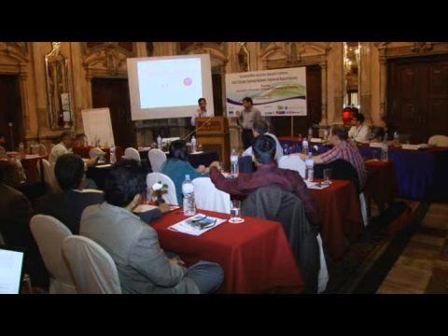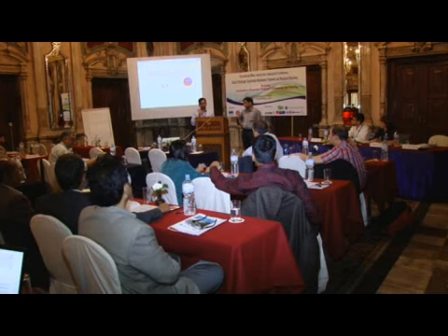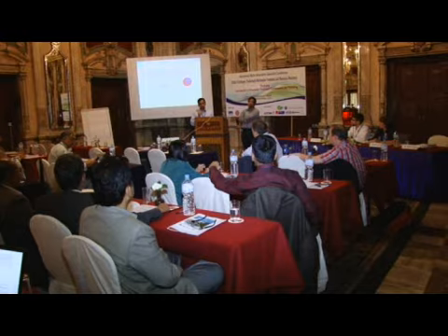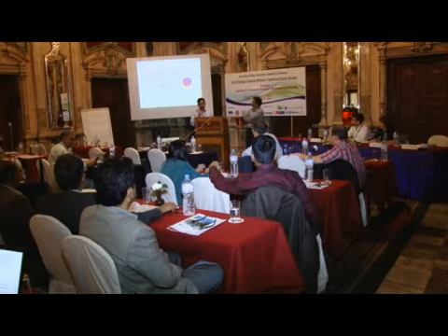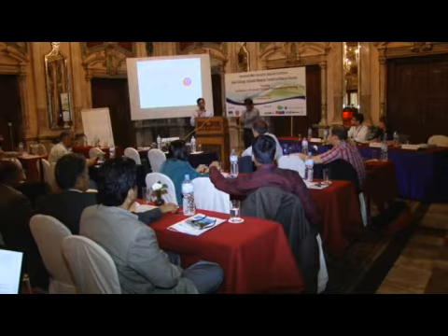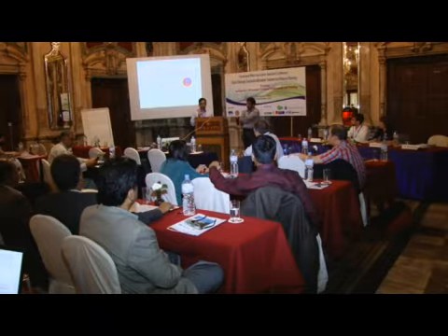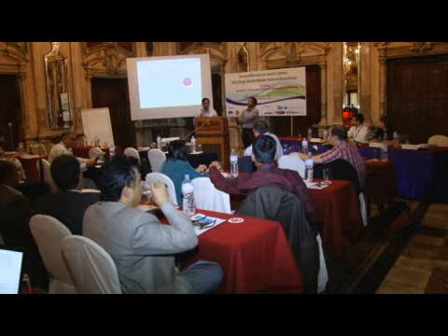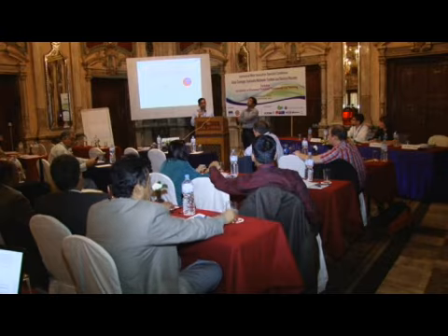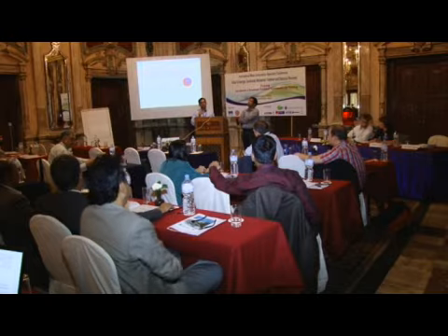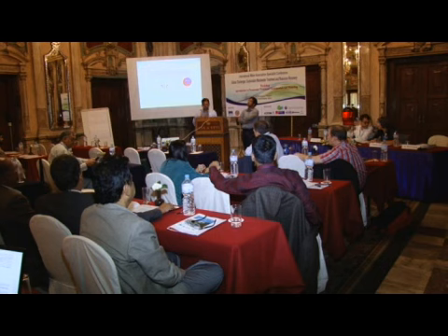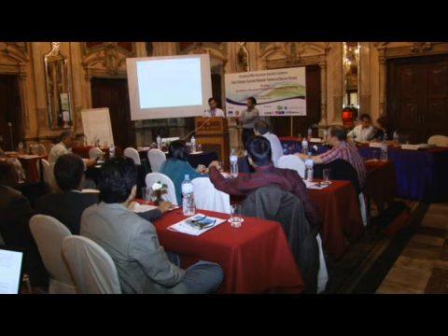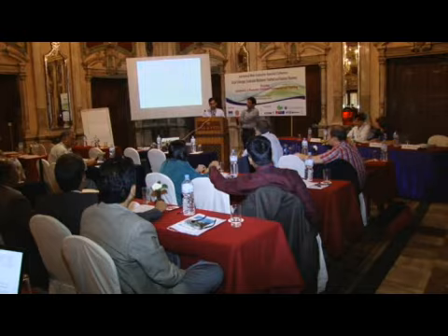There are some disadvantages of methanol, including lower kinetics, but we found in New York City that we had to shut down methanol operations because of safety, and we have since gone to glycerol. There are waste streams containing glycerol. As the biodiesel market accelerates, a lot of biodiesel waste has glycerol and traces of methanol as well. So that is something that has been tested. It's fairly widely applied. In some cases, what I would also recommend is to consider fermentation of some of these streams that I showed you.